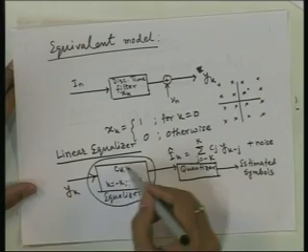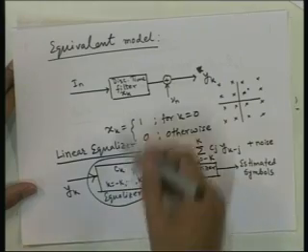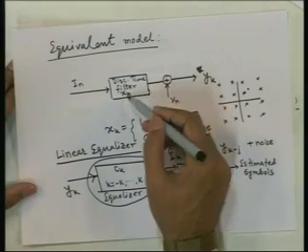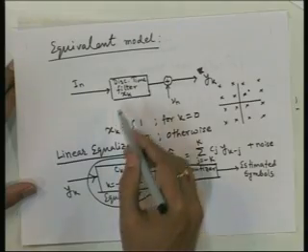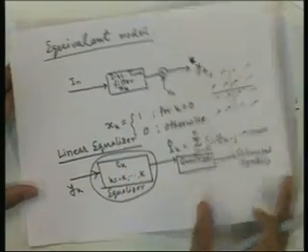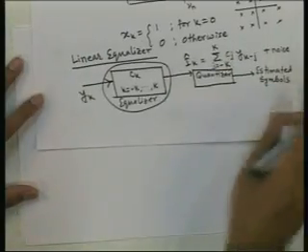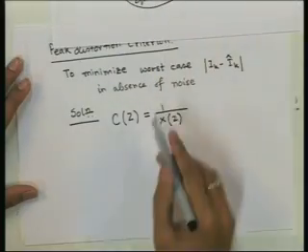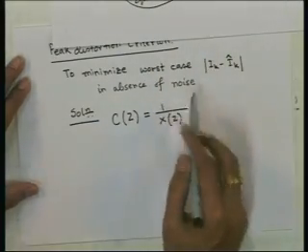What we want to take here is the inverse of this filter, that is 1 by X z. X z is the Z transform of x k, and C z, which is the Z transform of C k, will be chosen so that it is 1 by X z.